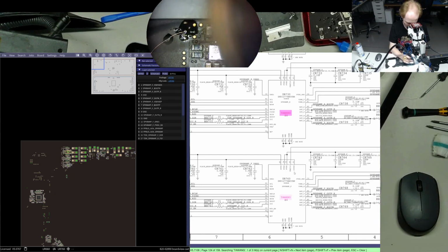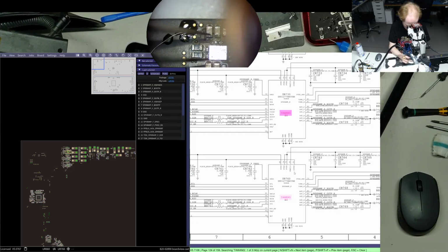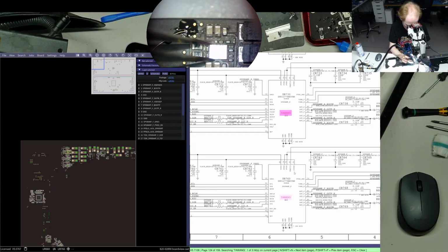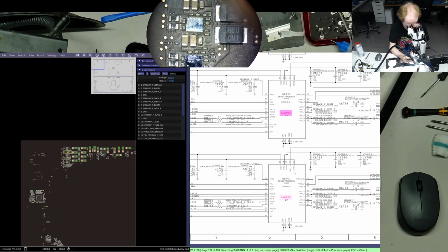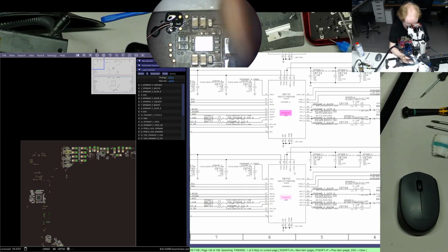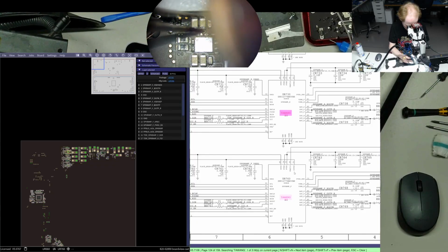So I think we found which one is the third one. The worst thing would be that it's flipped or not, but most likely that would be it, because we see some water damage here. Probably it wasn't even removed, so probably it has some dirt underneath it, because the caps don't look really nice, they're not looking healthy, and they should be replaced as well.